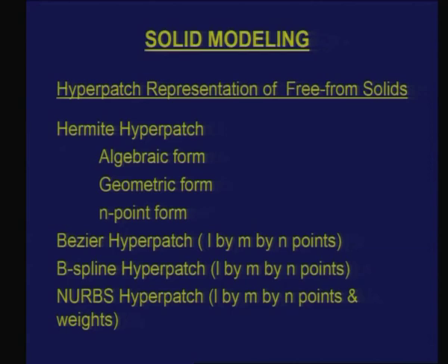the input in the form of 8 corner points of a hyperpatch, then first, second and other derivatives at those 8 corner points. If I provide this as an input, I can also construct a geometric form of a hyperpatch.